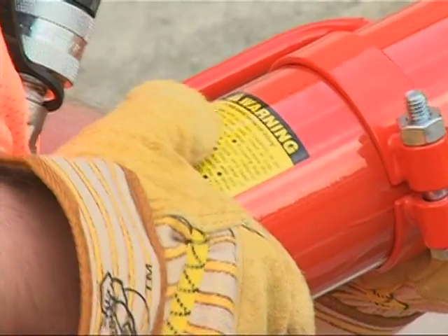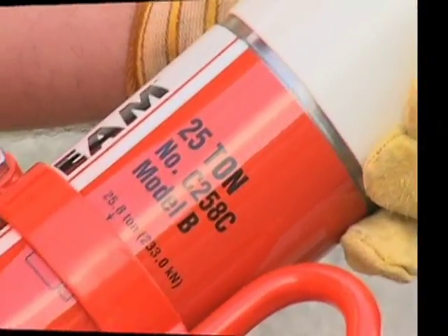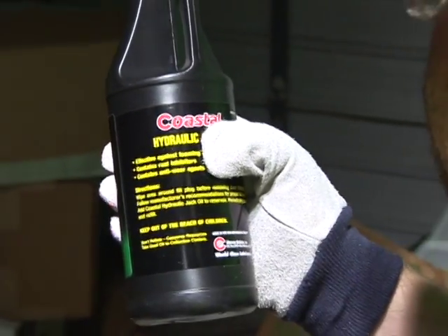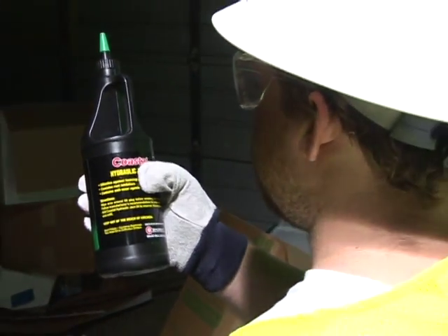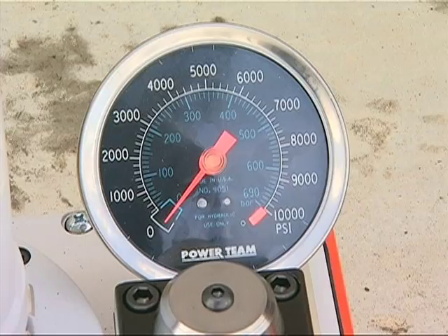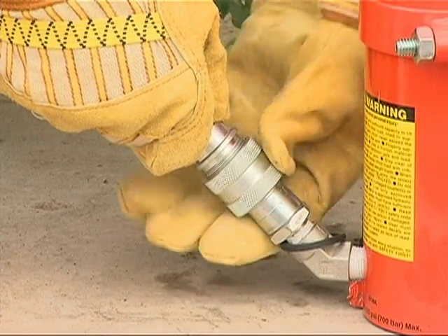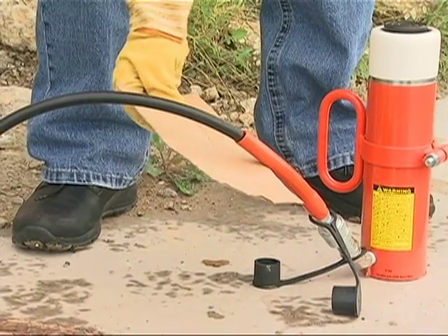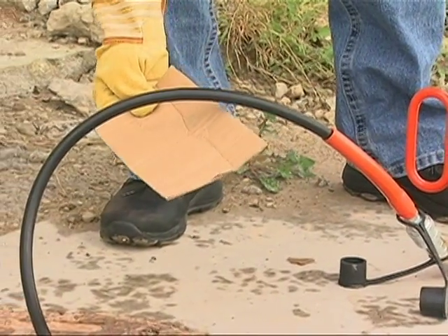The fluid used in hydraulic power tools must be an approved fire-resistant fluid and must retain its operating characteristics at the most extreme temperatures to which it will be exposed. The manufacturer's recommended safe operating pressure for hoses, valves, pipes, filters, and other fittings must not be exceeded. If working with a hydraulic tool, remember they are under extreme pressure and can cause severe injury.